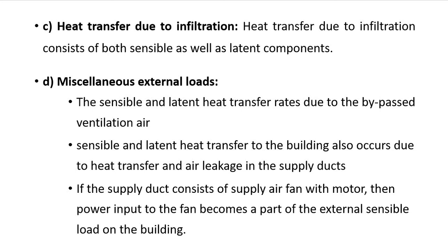And from the room, we are absorbing the air through return ducts, and the return ducts will go to the air conditioning plant, and that air will be again conditioned. So when the air is flowing through the supply duct as well as return duct, there will be heat transfer from the surroundings. So that heat transfer also has to be considered.